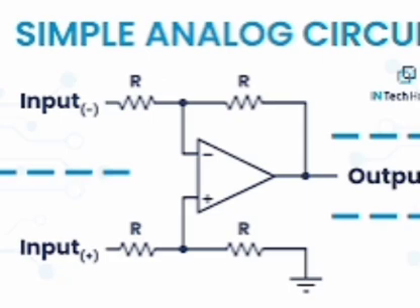Current amplification factor alpha: when no signal is applied, the ratio of collector current to emitter current is called current amplification factor or current gain. Alpha equal to IC by IE. Alpha of a transistor is a measure of the quality of transistor. Higher is the value of alpha, better is the transistor, as IC approaches IE. Collector current can also be expressed as IC equal to alpha IE plus ICB naught.